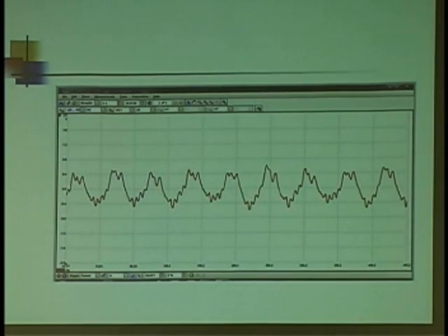Here's another example. Is that good or bad? Looks fairly uniform across the tops. Again, we're doing relative compression. I'm starting a drivability diagnosis, maybe a P0300, and I just want to go quick right offhand. Do I really need to worry about the engine's mechanical condition, or can I move on to something else? If I saw that, I'm moving on to something else.